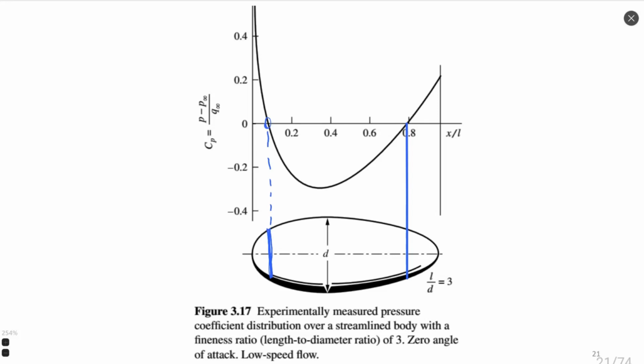So we have this oval body, and the installed Pitot tube could be at a point on the side of this body, on the front part. On the rear part, we cannot install a Pitot tube because it must be directed against the flow, right? The entrance must be against the flow. Since flow here goes in this direction, the Pitot tube cannot be installed efficiently, I think so.